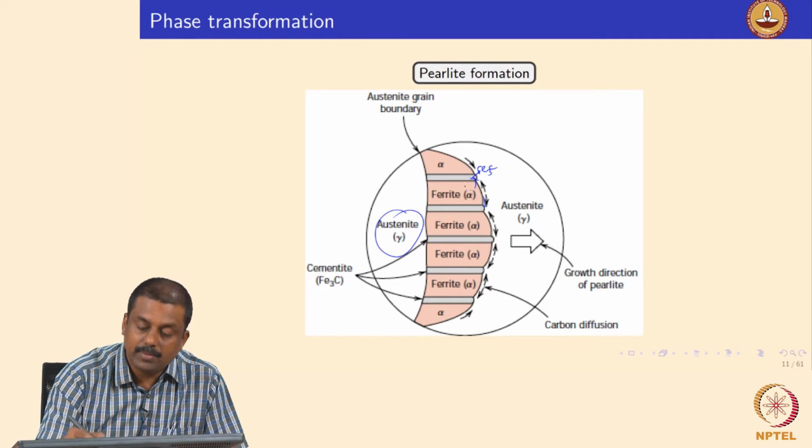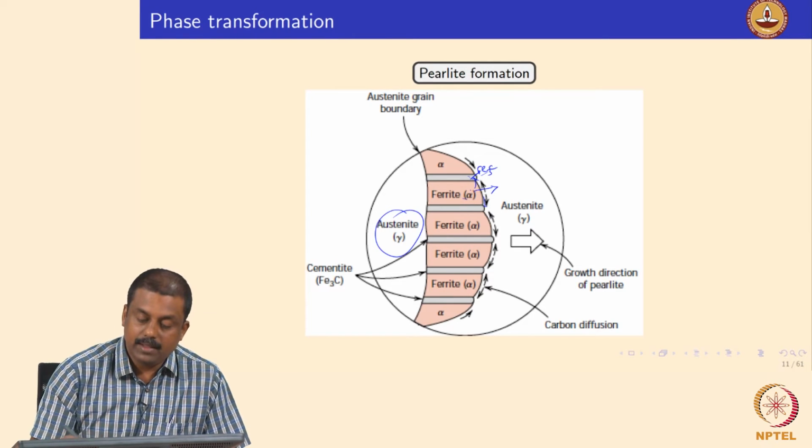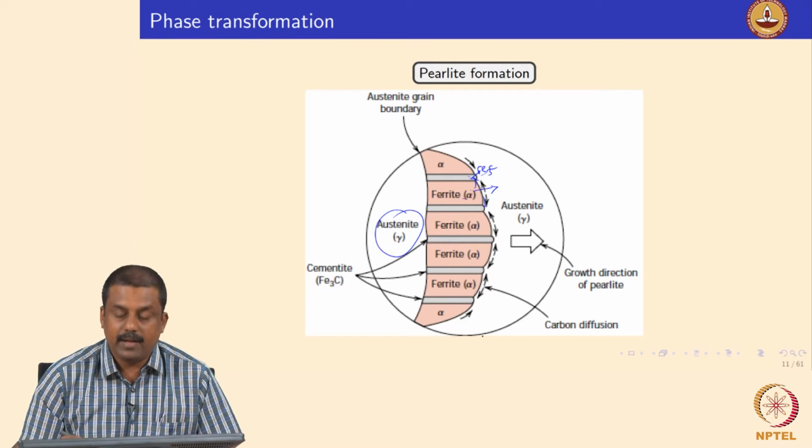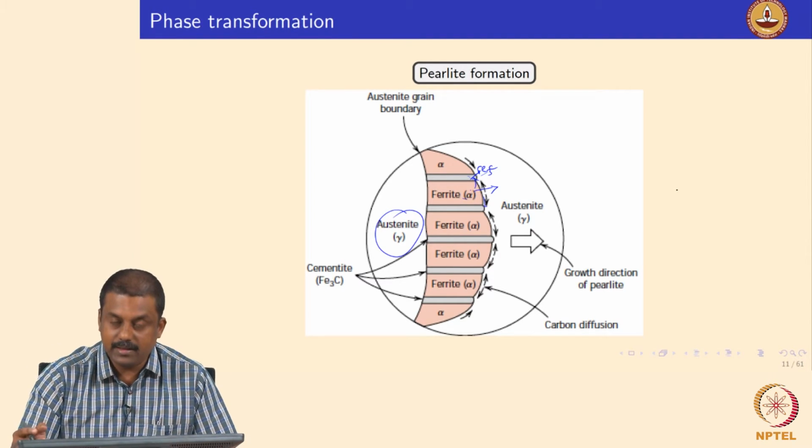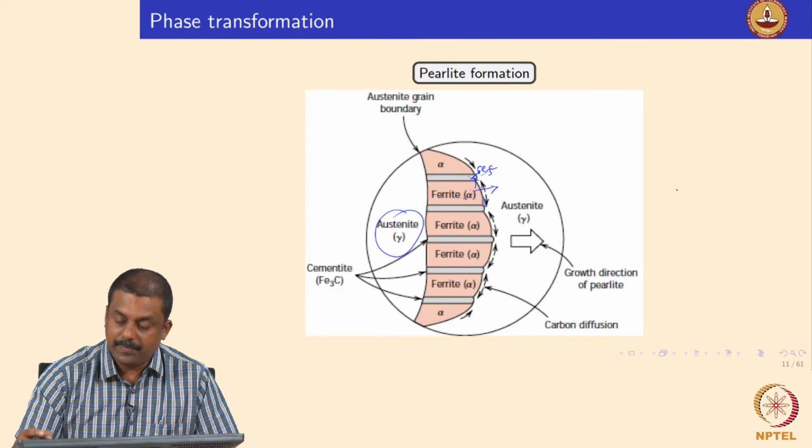Okay. So, subsequently this ferrite can grow by consuming austenite, and during this process the ferrite rejects carbon to adjoining regions, forming cementite lamellae, ferrite-cementite lamellae, as explained in this figure. And this happens, you can say, close to equilibrium, when you do not have high cooling rates as well as high alloying elements.